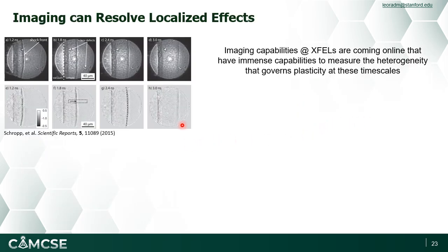We can then go a step further, and we can even ask ourselves, what exactly, beyond just the phase of the crystal in any little spot, how does this manifest as heterogeneous behavior of this material itself? So we can now actually also use microscopes, X-ray microscopes, to be able to zoom in and see things like our shock front that's propagating, the elastic front versus plastic front as they propagate, and to start to watch more subtle heterogeneous behaviors.